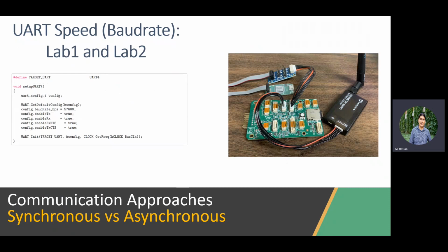So the way we do this in lab 1 is you will interface with our laptop terminal. You write a command in the terminal on your desktop or laptop, and this command will be sent over a UART communication to this transmitter, which is a wireless transmitter. So we'll have 2 of these transmitters. One is attached to your desktop, another one is attached to the FMU itself.